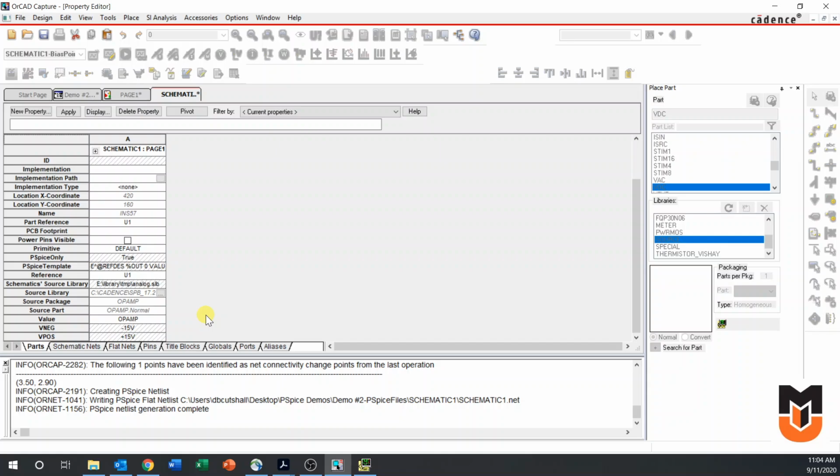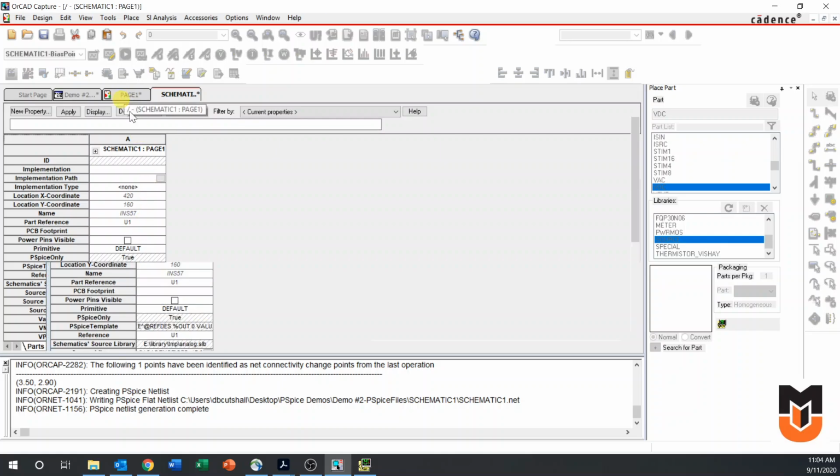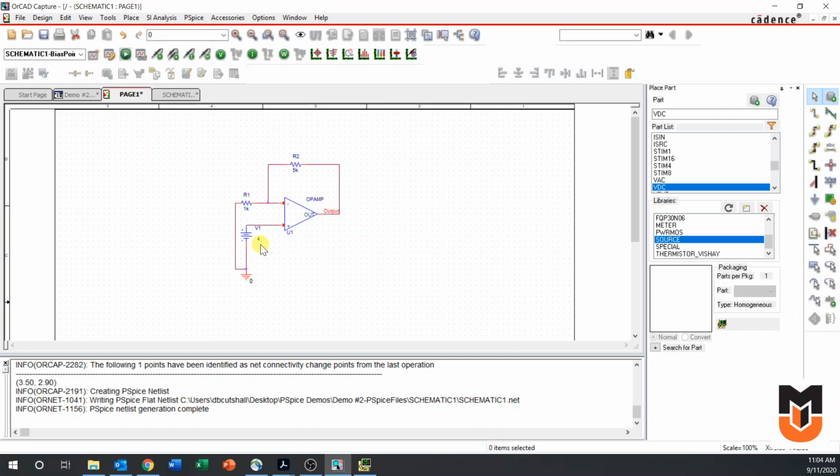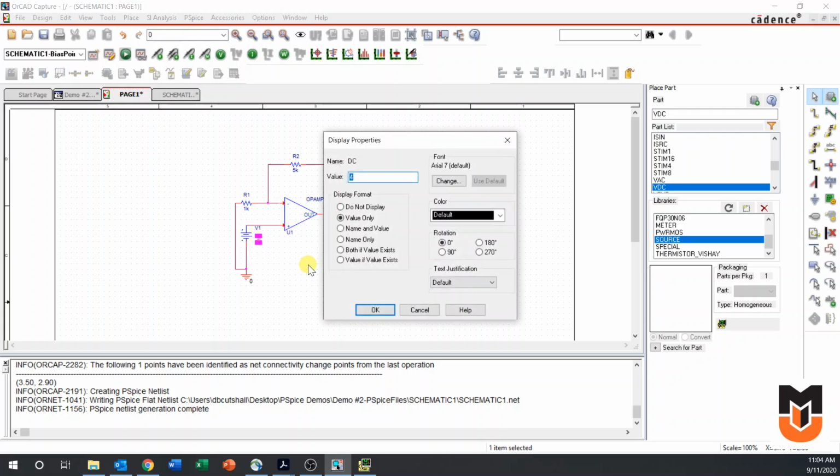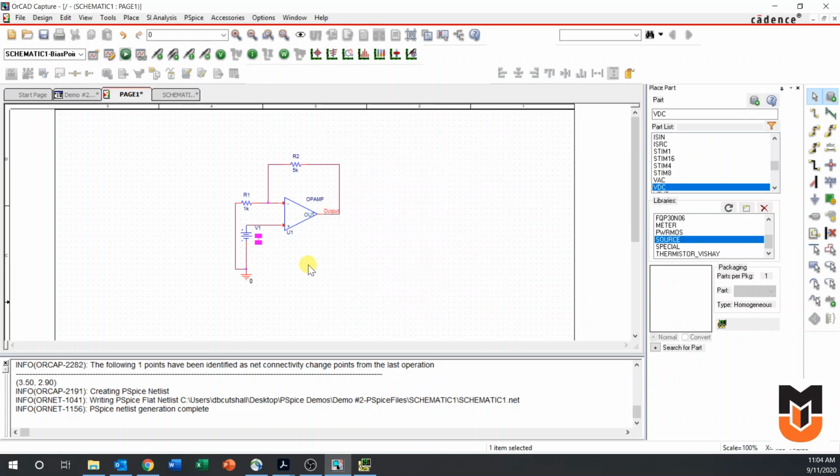Like I mentioned, in this case, it's a simulation, so we're not going to hurt anything. We could take this up to 500 volts if we wanted. But for a real op amp, you might not want to do that. So let's, for instance, just leave this at plus and minus 15 for now. Again, you could change that if you wanted. But let's instead just change this input down to, let's say, 2 volts.